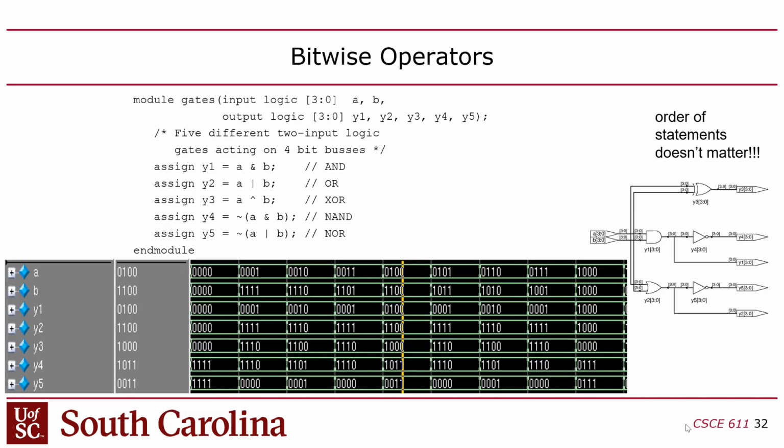Okay, and then there were some syntax things we covered last time, multi-bit signals. I pointed out that when you declare a multi-bit signal, you put the bit range before the identifier, which is different than what you're used to. And I often forget, and I put it after. Notice too that every time you want to have, say, a 4-bit signal, you have to say 3:0. So you take the number of bits, you subtract 1, and then you put a :0 behind it.